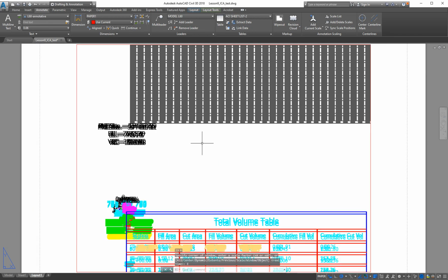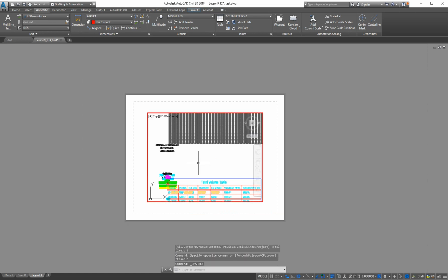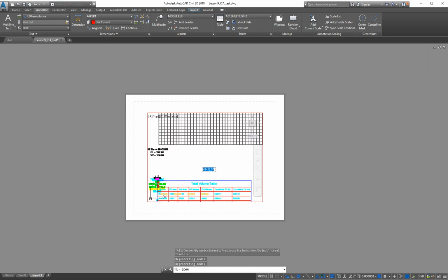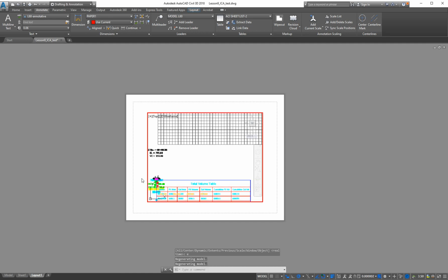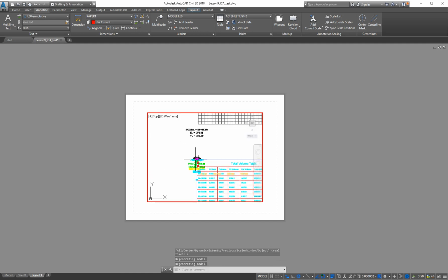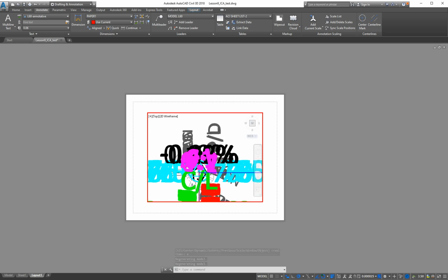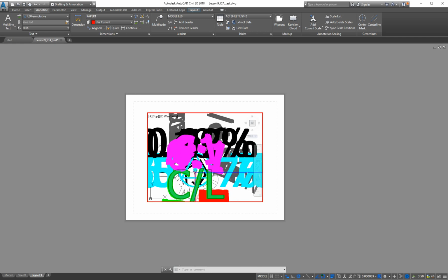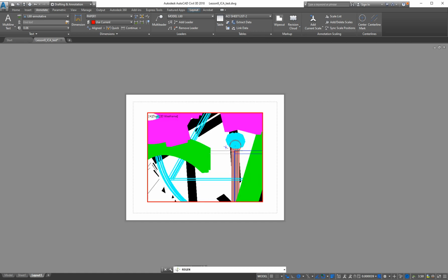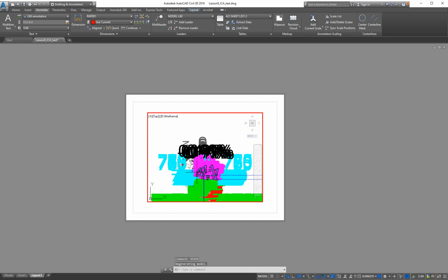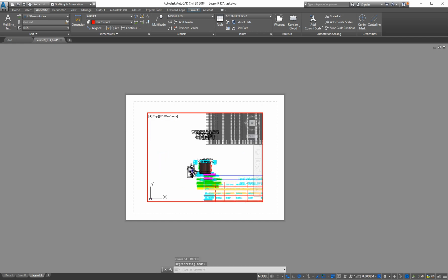So yeah, it's zoom extents. Okay, well, I was in paper space still. Let me get into model space, zoom extents. Okay, and the road, I can tell you right now, is buried under this stuff, and we're going to zoom in. And then we're going to use our favorite new command, regen. Come on, regen. I'm going to zoom in a little bit more. Regen again.